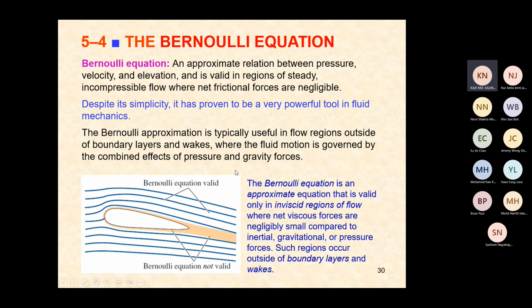You see the wake region is here, and then the separation and reattachment region is this. After all this region, Bernoulli's equation is not valid. Rather, it is valid outside the boundary layers. It is valid here, and you see the flow streams are moving on here outside the affected region. Bernoulli equation is not valid here, rather it is valid here in this case.